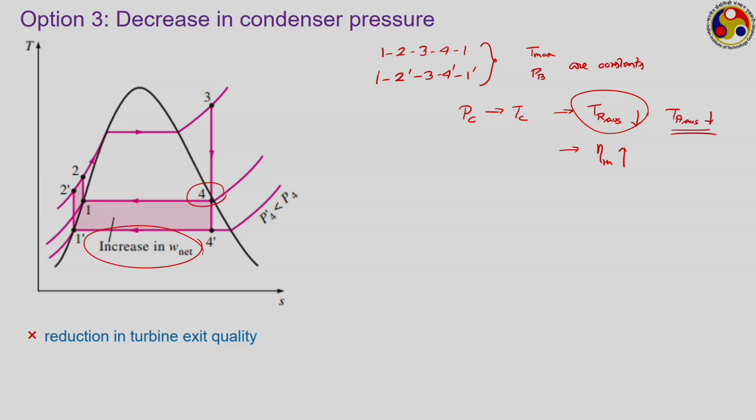and also a practical difficulty, that is, the pressure maintained inside the condenser is generally well below the atmospheric pressure, because we select the condensation pressure based upon the atmospheric temperature. Now, you know that for water at atmospheric pressure, the saturation temperature is 100 degrees Celsius. Then if we want to attain condensation at, say, a temperature of 20 degrees Celsius, we have to reduce the pressure significantly below atmospheric pressure.